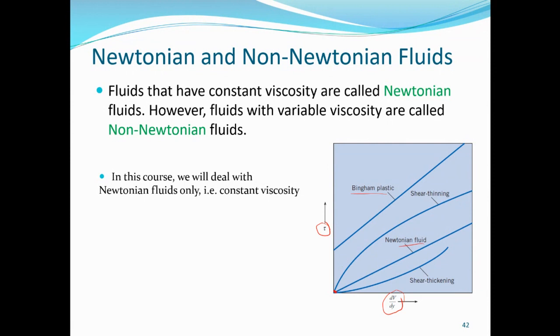Okay, so a Newtonian fluid is one that obeys Newton's law of viscosity, which is the fact that the shear stress is proportional to the velocity gradient. When you remove it, you have a constant dV/dy. So the viscosity, mu, is constant for a Newtonian fluid, while for a non-Newtonian fluid the viscosity is not constant. The viscosity, mu, is simply the slope of the graph.